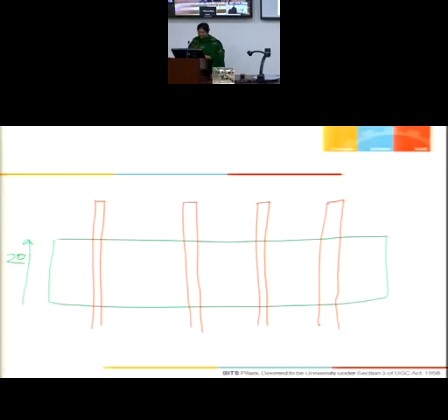And then all the gates must be common, because all transistors must be connected in parallel. So their gate should be common. They should have a common gate. So this is a common gate. This is a common gate. All fingers are connected together. That is why the name is multiple gate fingered layout. Now, once this is done, I have to have all 4 transistors with drain the same, gate the same, and source the same, because they have to be connected in parallel.